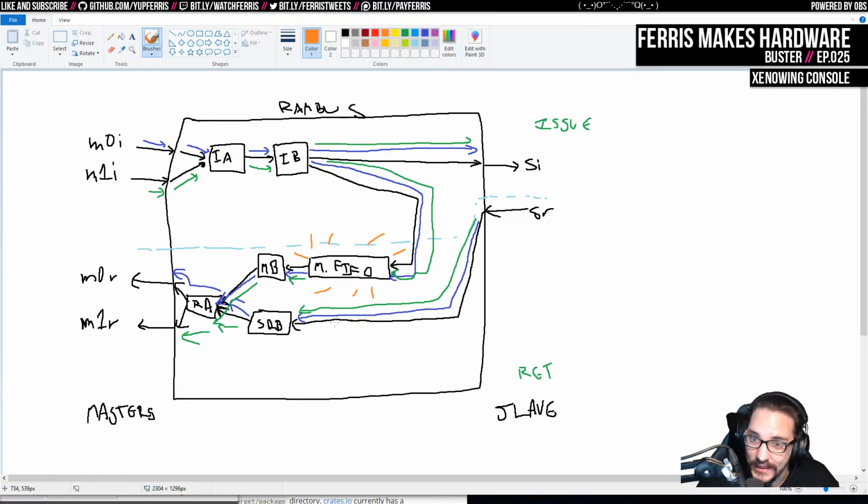And then the other thing that I didn't talk about here is, what if these are issuing writes in the meantime? And that, I think, is just a non-issue, because if it can issue writes, all this buffering and everything is still going to block the write, except I think we can issue writes without caring if this Fifo is full, which is nice. So writes can just slide in here unnoticed. And then the rest of the system doesn't have to care, because the slave's not going to return any data for writes. So writes should be a trivial extension is kind of what I'm getting at.